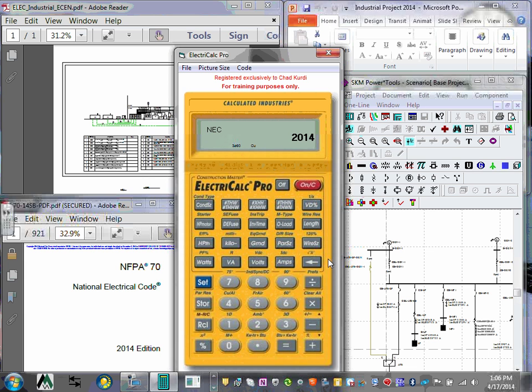Okay, how many conductors, say 5 or 6 conductors number 12 THHN plus 3 conductors number 10? I'm going to put them in a conduit. Just say that we typically don't do that. What size of conduit, EMT conduit, do you need? In a couple of clicks, it's there. So you need to spend 4 hours though to use it professionally.